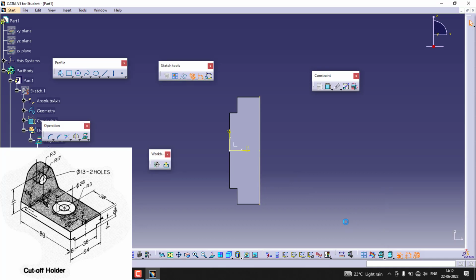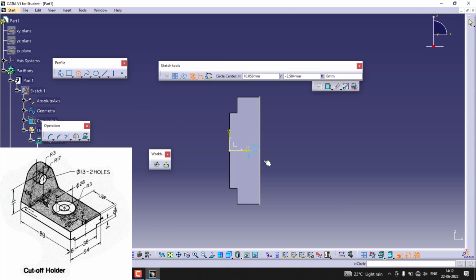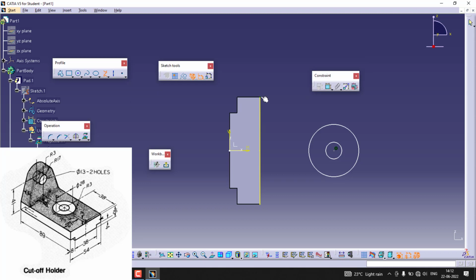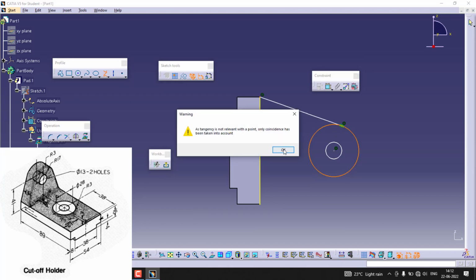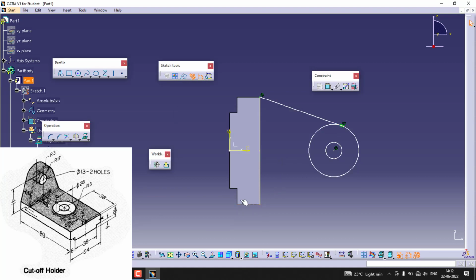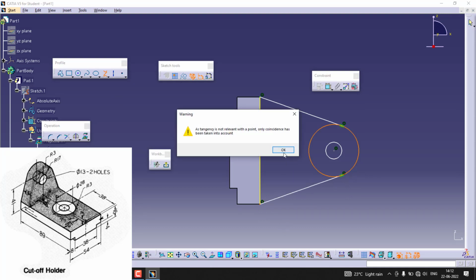Okay, yep, so we have the reference axis, so you can simply draw the circles now, two, and then I need the tangent lines. Instead of profile, you can use this option. We have this advanced tool, that is by tangent. So wherever a single tangent is required, you can use the same thing, and it will automatically convert the tangents. You can see it shows there are no by tangents, single tangents is enough.